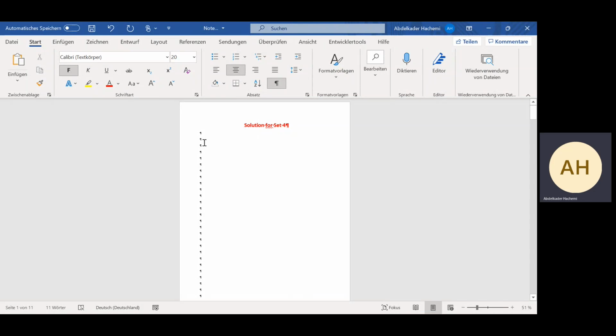We know that to determine graphically the instantaneous center of rotation, we need, as in the previous example, the direction of 2 velocities. We know already one, which is given in the exercise. It's VA, it's horizontal, that means we have to make only the perpendicular to it. And we have to look for the second one.